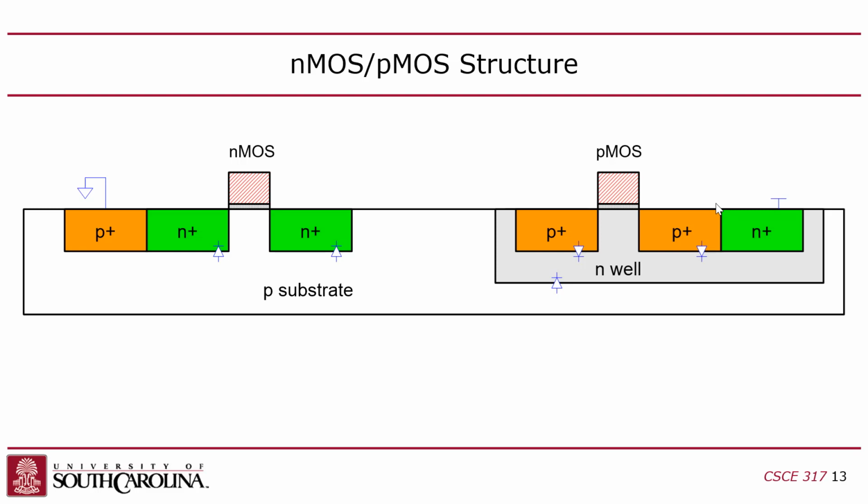And you might say, well, then what's the point of that? Well, it creates a nice contact. You have a wire that's metal, copper, aluminum wire, and you want to connect that wire to silicon that's more conductive. So I'm going to dope it really hard with P. And then I will embed it in a more lightly doped region. So this creates a nice path into the substrate, right?